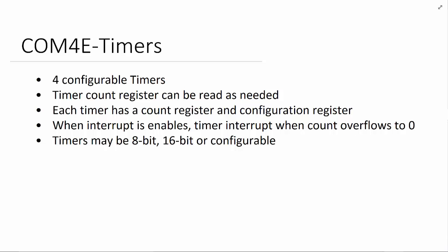In this video, we're going to talk about timers. Timers are very useful in that they allow the processor to determine, without having to sit in a loop and count the number of instructions, how long things are taking. We can turn on a timer and read it to figure out how long has gone by since the start of the timer.